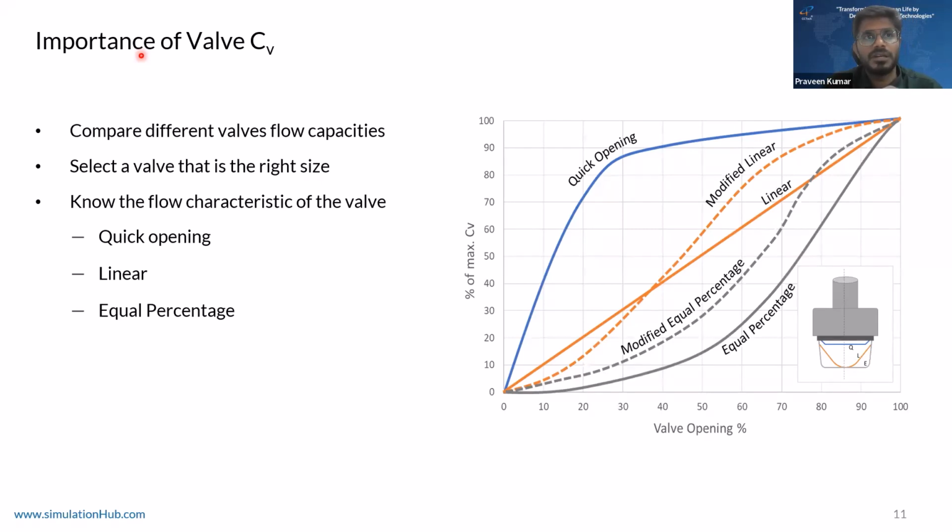If you have improperly sized, oversized or undersized your valve, then it can cause a lot of damage to the valve. It can induce cavitation as well, because if you oversize your valve, most of the operating time ends up with your valve operating at a lower angle of opening or percentage.